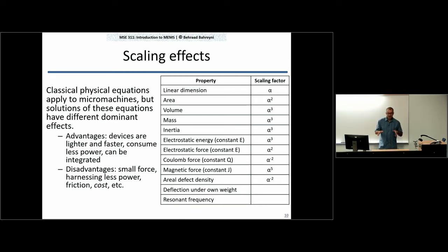So if you're making these devices in parallel, if you're putting 100 of them in parallel, and let's say you have 50 particles that fall off and kill 50 of your devices, if you make your devices smaller and put 1,000 of them in parallel instead of 100 of them, and you drop the same 50 particles, 950 of them will survive your new devices. So this is another motivation to make your chips, your devices smaller. You make more of them so you make your money, but also fewer of them will have yield issues.